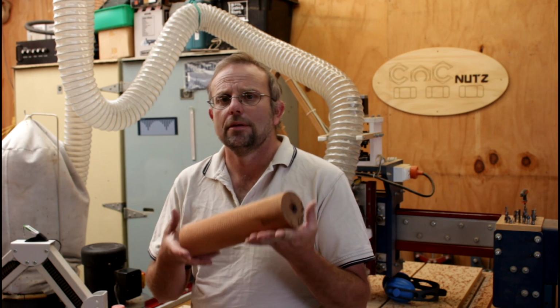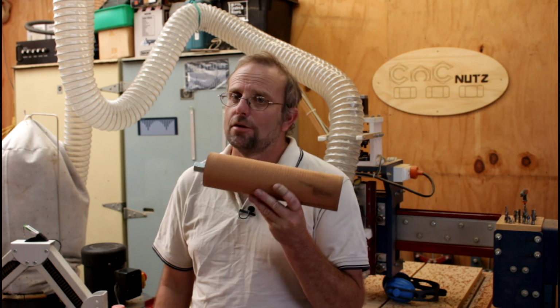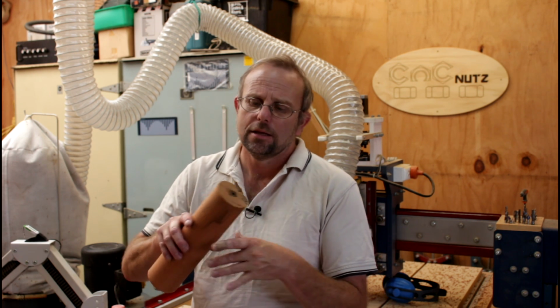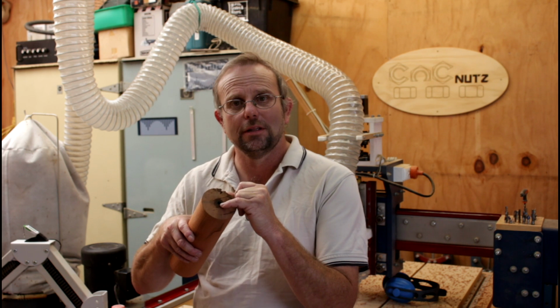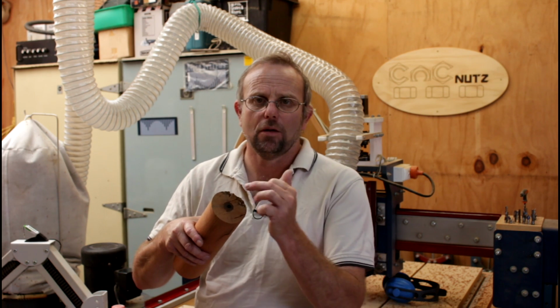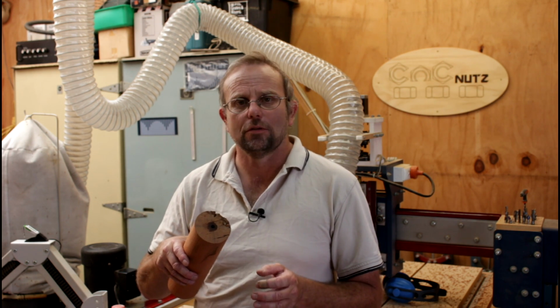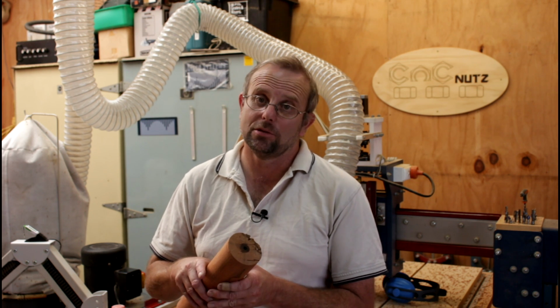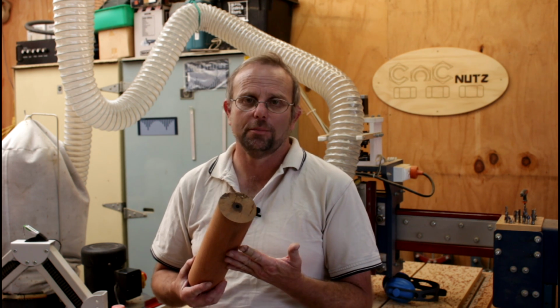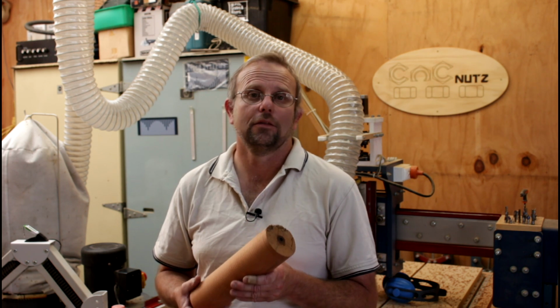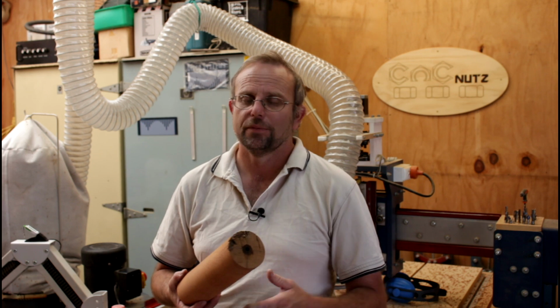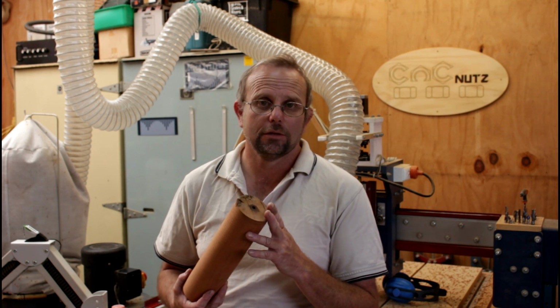So here's a little tip for making this run a lot quieter on your machine: where the tailstock goes into the end of the material here, put a little drop of oil. I just got a little drop of oil out of my oil can into the little hole where the tailstock sits, and that really quietened the thing down, became silent. Before that it was squeaking something terrible, it was driving me around the twist. Tiny drop of oil and the noise goes away. It runs a lot smoother as well. And it doesn't matter that the oil soaks in, because it's going to be cut off anyway at the end of the day.